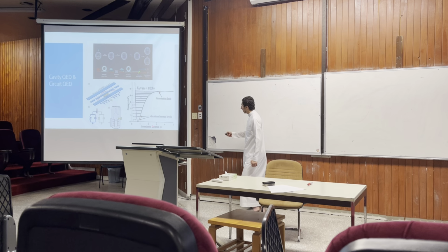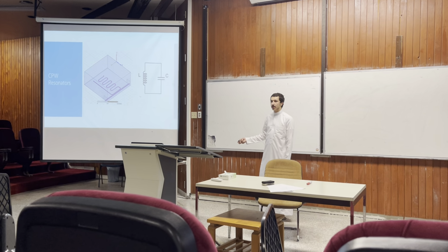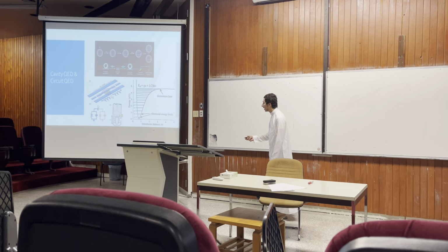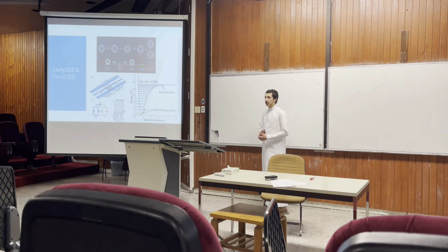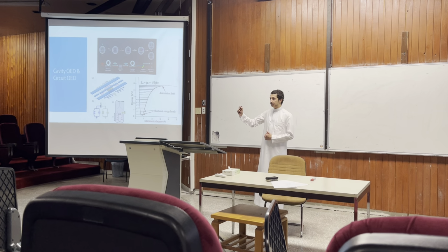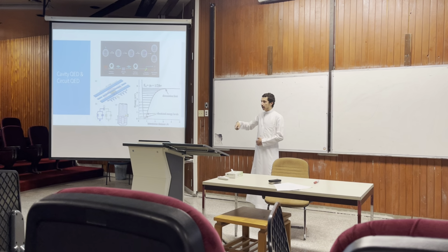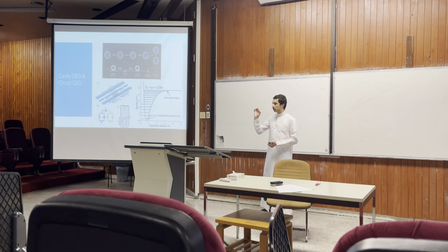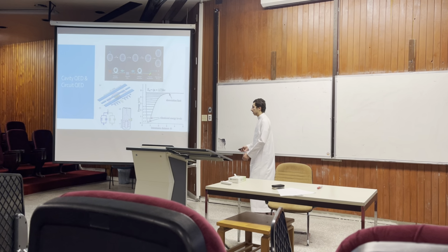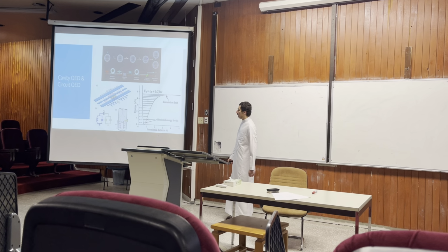And how we apply this, because we know that an LC oscillator can act as a harmonic oscillator, is we change it to a nonlinear LC circuit. The nonlinearity comes from the inductor. So we change the inductor into a nonlinear inductor, which we call a Josephson junction. And all we need to know for today is that the nonlinear inductor is a superconducting inductor. We can almost view it as.